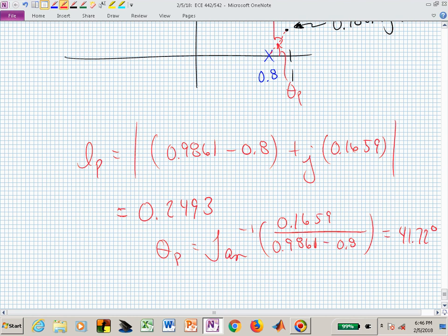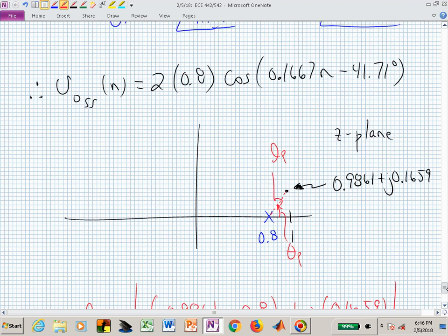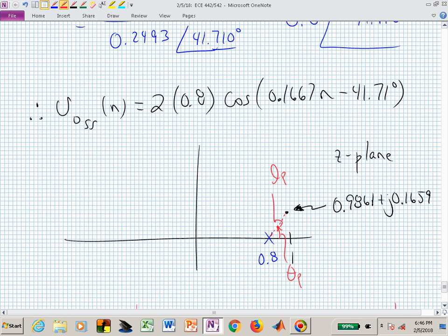And you could compare this discrete time answer. This is now 1.6. That before this time shift, wasn't it about 40 degrees in the continuous time setting? And what was the amplitude? 1.5 something? So we're doing about the same with this discrete time low pass filter in a difference equation as we found in the continuous time setting.